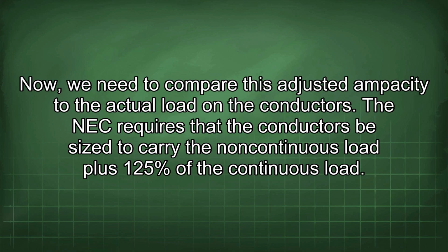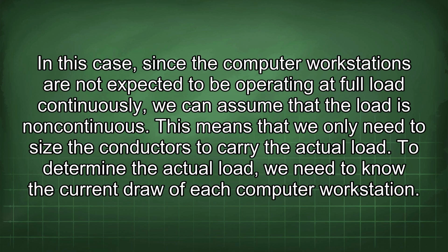The NEC requires that the conductors be sized to carry the non-continuous load plus 125% of the continuous load. In this case, since the computer workstations are not expected to be operating at full load continuously, we can assume that the load is non-continuous. This means that we only need to size the conductors to carry the actual load.